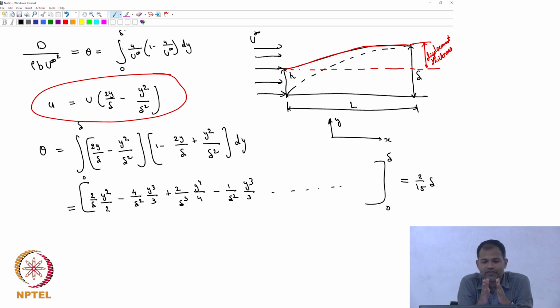So typically, whenever you have flow in very thin sections, an approximation of a parabolic profile often gives you good results. So that's the only reason. We could have done the same calculation assuming linear, okay, and you would have gotten a good estimate. Parabolic is slightly better, because the actual profile is very close to a parabolic profile.